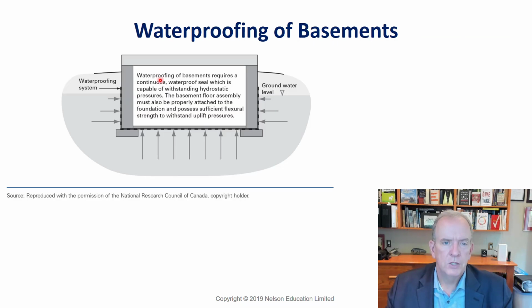So waterproofing, as I mentioned, hydrostatic pressure can pretty much move anything. It's got a lot of power. It's why we've got to do our formwork really well, as I mentioned, because when the concrete is very plastic, it has a lot of hydrostatic pressure that it puts on the forms. Once it starts to set up, there's no pressure. But when it's being poured, there's a lot of pressure.